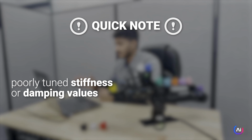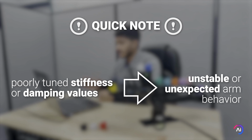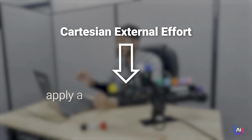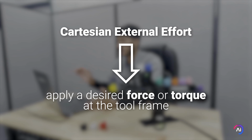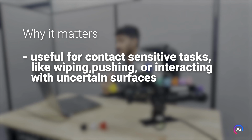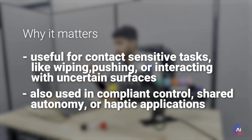Poorly tuned stiffness or damping values can lead to unstable or unexpected arm behavior, so adjust with caution. And finally, we have the Cartesian external effort mode. This is used to apply desired force or torque at the tool frame, often used for force control tasks. This is useful for contact-sensitive tasks like wiping, pushing, or interacting with uncertain surfaces. Also used in compliant control, shared autonomy, or haptic application.